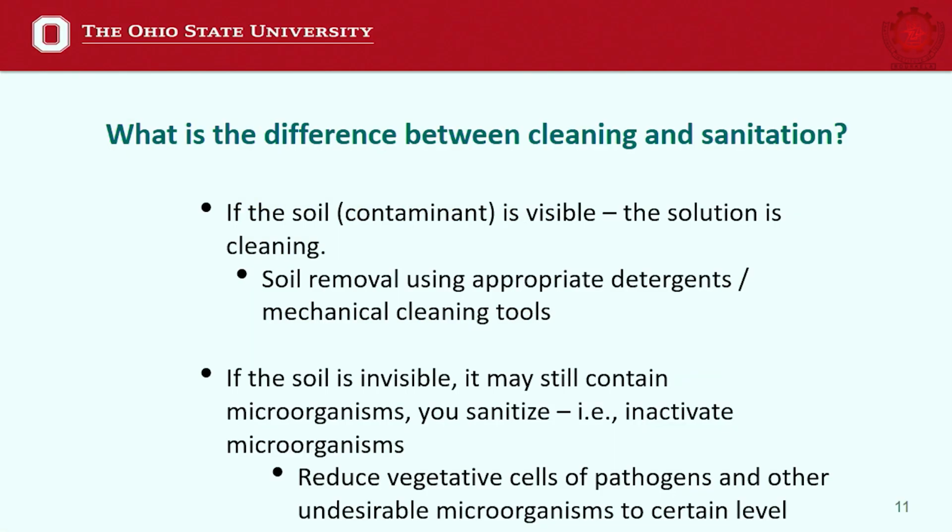Now, is cleaning the same as sanitation? Sanitation refers basically to getting rid of the microorganisms to a certain target level, whereas cleaning primarily refers to removal of the residues, your protein films, things of that nature during the process. So, the soil is visible, and then you clean it. On the other hand, once you clean it to the extent possible, there is still a possibility of microorganisms attached to the surface, even though the surface looks visibly clean. So, you have to sanitize.